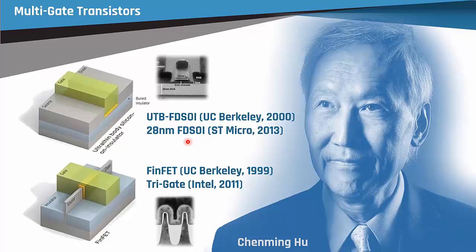And so that is one of the types of transistors that he invented. It's actually what you could call a back gate transistor or a double gate transistor, where we make the transistor, instead of on a regular substrate, we put a piece of silicon dioxide underneath it, or we use a wafer that has it like that, and it has a very thin body, so the drain and the source are fully depleted all the time. This is able to reduce leakage in all kinds of ways, because leakage can't go through that big piece of oxide underneath, and because we're able to bias the gate in a way to change the threshold voltage.